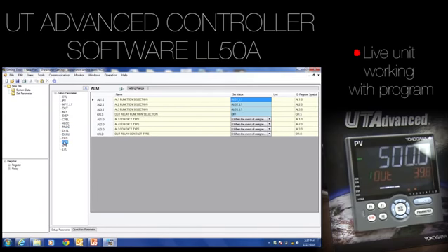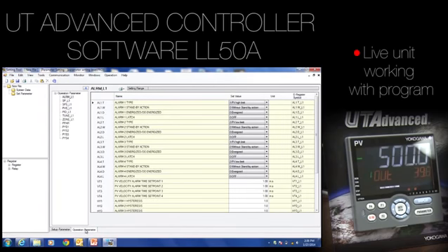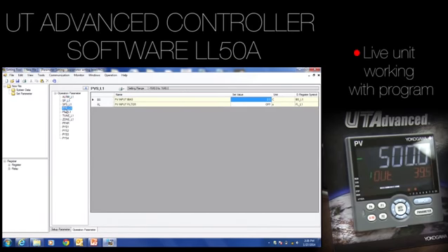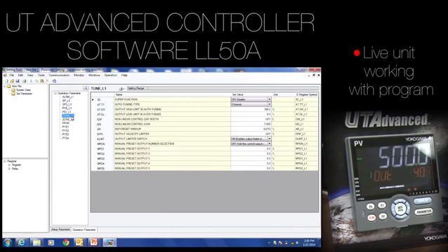So these are really nice as well. Digital input selections, the alarm settings, all these. So these are all your setup parameters, and basically these are going to be the base settings for your controller going into the application. So these are going to be set up one time. Once they're set, you come out of the menu, you don't set them again. Then you have your operating parameters, which are things that are going to be changed on a regular basis. So like your alarms, your set points, your PV parameters like your bias and your filter. These are things that a customer may want to change on a regular basis. Your PID parameters. So your tuning menu.